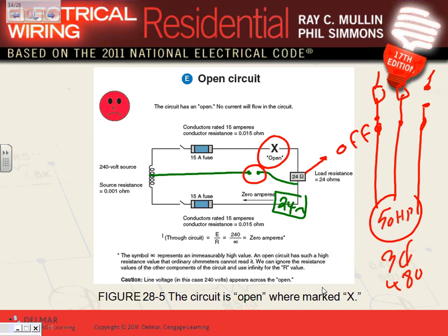If this motor is running, guys, you know what happens? The motor starts sucking more current out of the two other phases, and the other two phases will be overloading unless you have an overload sized right here. This is my overload. This will be carrying close to 130%. This will also carry 130% or so. So this will be zero, right? 0 amp going through. It's open. So you're overloading the other two phases.